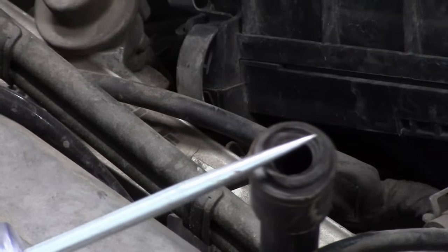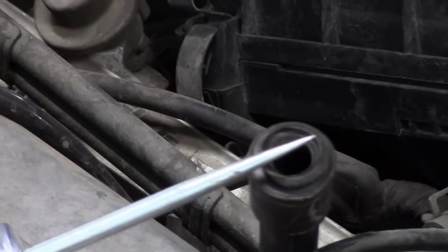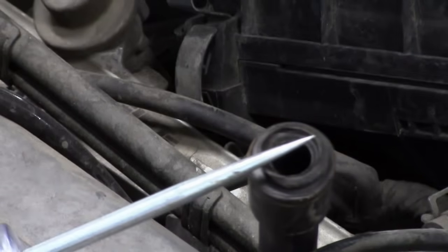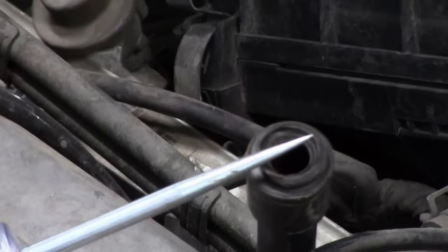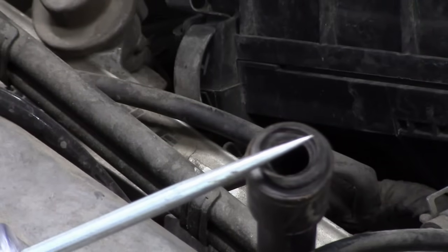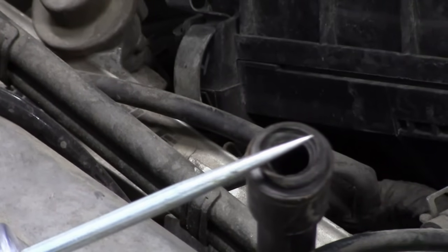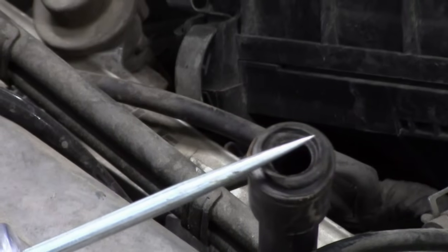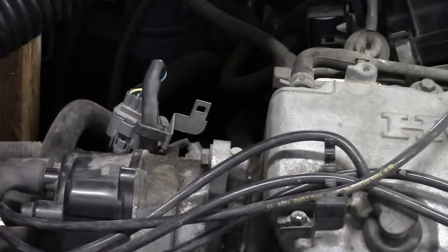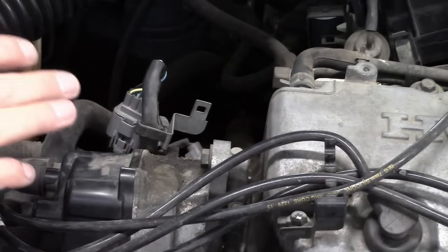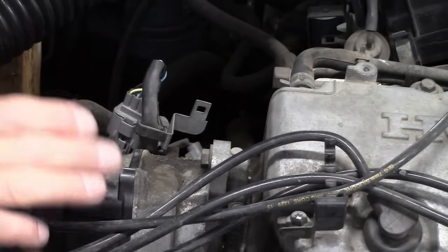All right, you can see there's no spark there. Hopefully also that compression issue is more apparent. Again, not the cause of the no start, because we would still hear the engine trying to start from the other cylinders, and it would just have a miss in it. That is no spark. And then, of course, what I did was go over to the distributor. And actually, I lied. I didn't, of course, immediately go to the distributor. There would be no reason to do that.